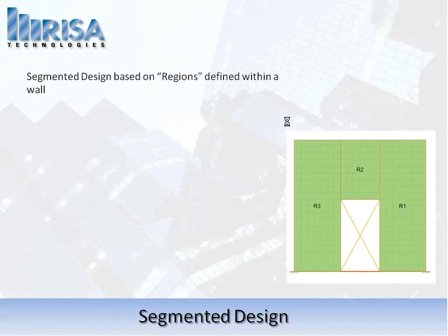So when we run the model here, when we run walls, in particular we have 3 different types of walls that we can do. We can do segmented, perforated, or force transfer around openings. And we'll start with segmented. Okay, this is actually where RISA began, with a segmented wall without openings. So we'll talk about segmented to start. And the way we talk about segmented is it's based on regions.